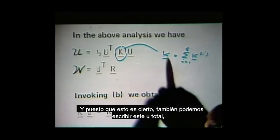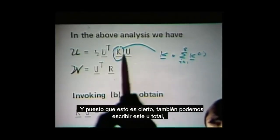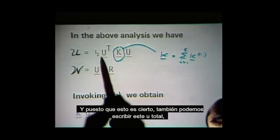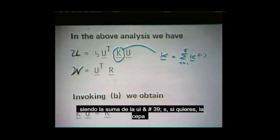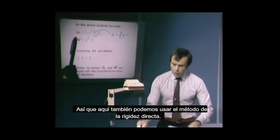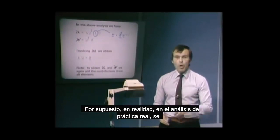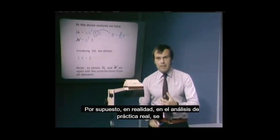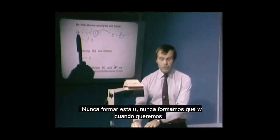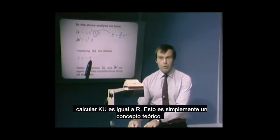And since this is true, we can also write this total U as being the sum of the UIs, if you want to, the strain energies of all of the individual elements. So here too we could use the direct stiffness method. Of course, in actual practical analysis, we never form this U, we never form that W when we want to calculate KU equals R.